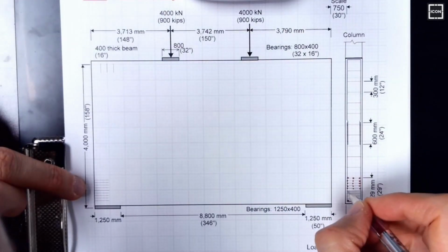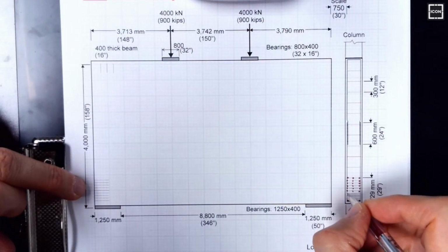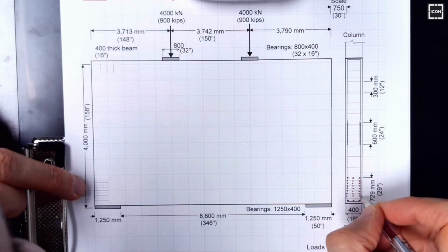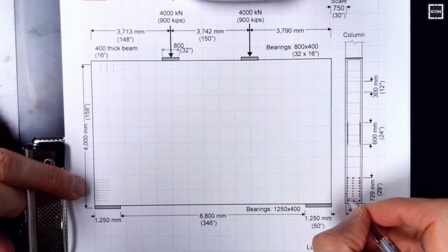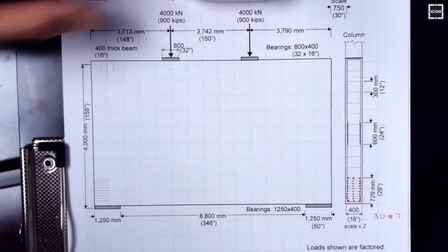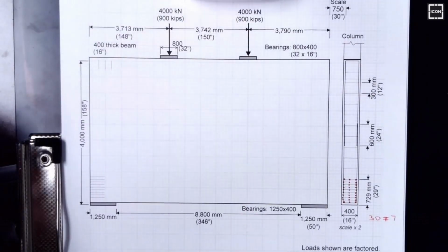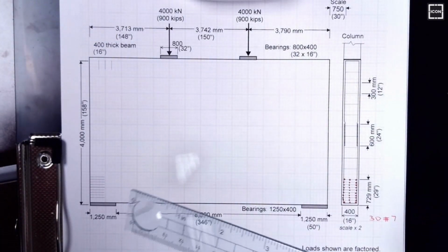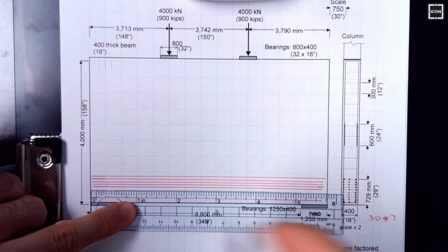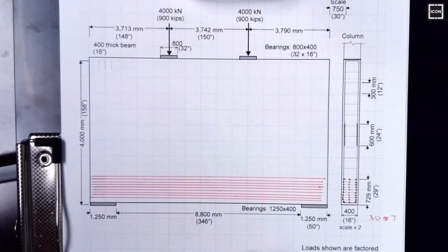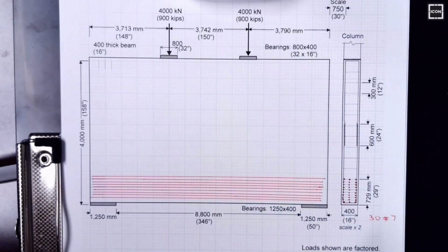As you can see, you can design a bridge element by hand calculation fully without using computers, and your design would most likely be better than your computer sectional design, because there are so many details you are considering which computer or sectional design wouldn't even consider at all. The minimum the amount of hooks, the happier contractors are. So this is the main reinforcement. That's pretty much it. That's the full design.